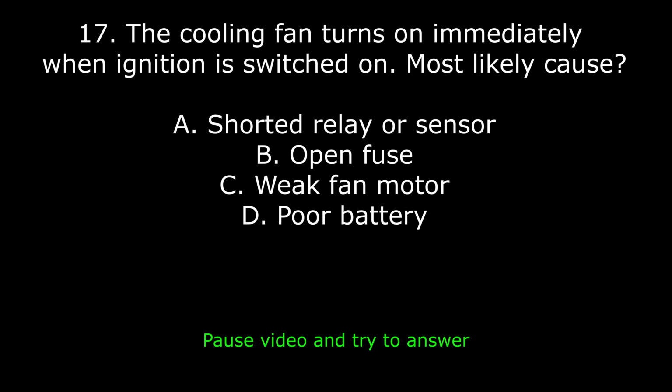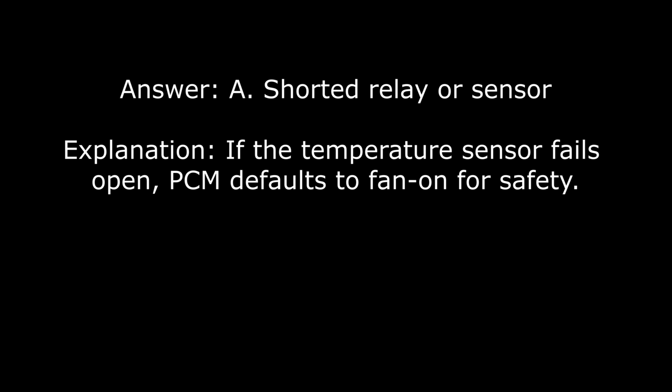17. The cooling fan turns on immediately when ignition is switched on. Most likely cause: A. Shorted relay or sensor. B. Open fuse. C. Weak fan motor. D. Poor battery. Answer A. Shorted relay or sensor. Explanation: if the temperature sensor fails open, PCM defaults to fan on for safety.